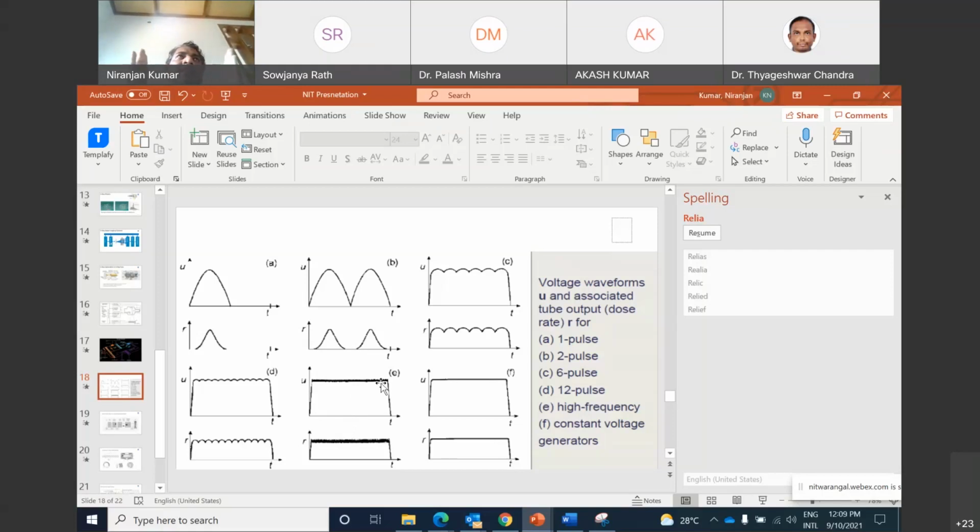Then you can control the way you want the kV level to change through that technology. And if you go to the Pierce gun, I can control that electron cloud the way we want. So at the end, you can take this graph the way you want, with separate control of mA and separate control of kilovolt.